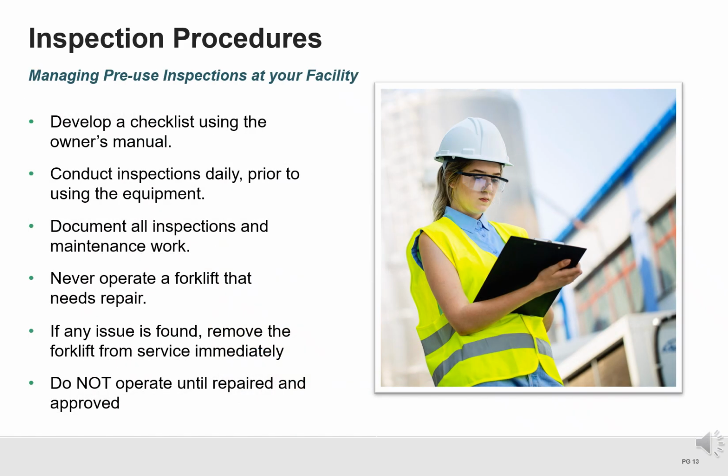Pre-use inspections are required before operating a forklift. Use a checklist based on the manufacturer's guidelines and complete the inspection daily. All inspections and maintenance must be documented. Never operate a forklift that needs repair. If any issue is found, remove the equipment from service immediately and do not operate it until it has been repaired and approved.